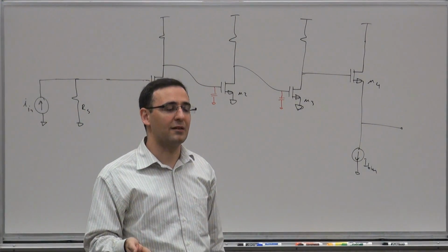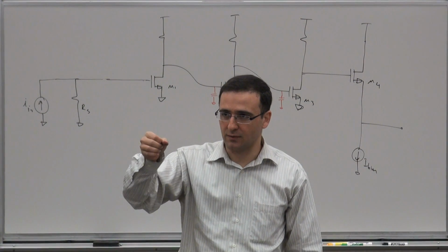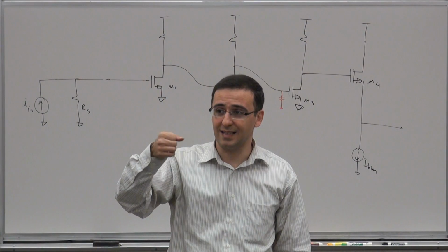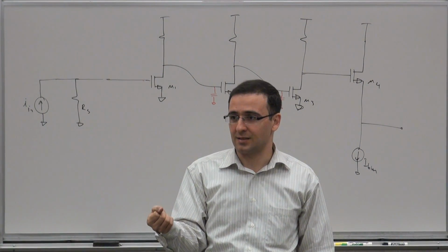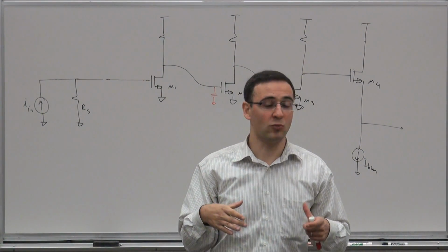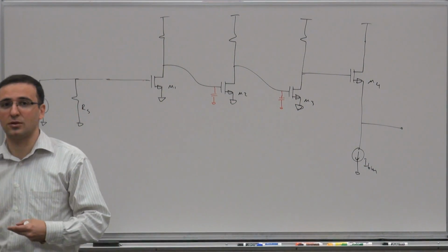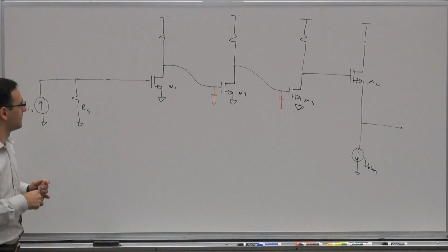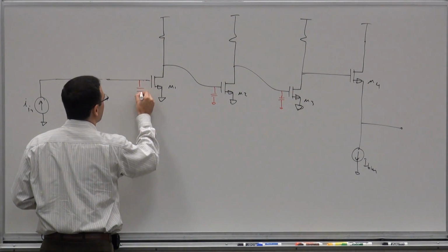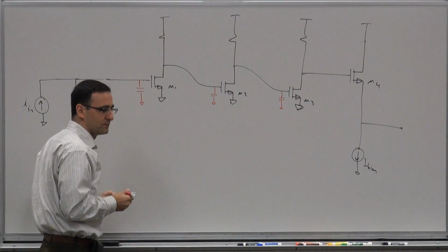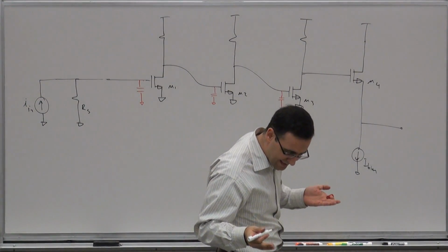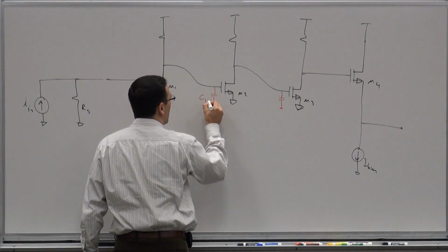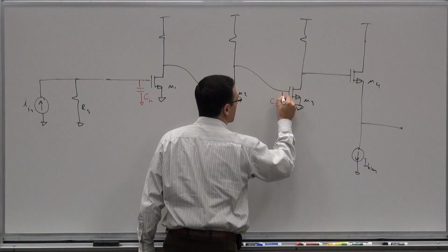There's a trade-off there: if you make the surface of the photodiode small, it will have less sensitivity but smaller capacitance. If you make the surface very large, you generate more current for the same intensity, but you will have larger capacitance. So overall, you have a capacitor here which is the combination of these two. Let's call them Cin, C1, and C2. Stay consistent.